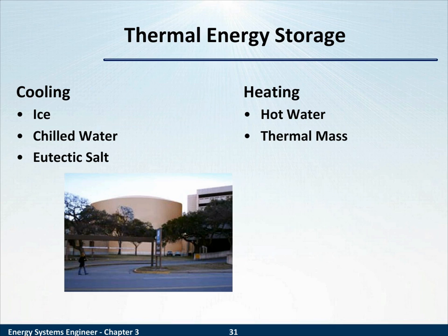We have now a couple slides on thermal energy storage. Something to consider right off the bat is why thermal energy storage. Thermal energy storage does not save in energy consumption. If you were to create cold water, store it in this big brown tank in the picture, and then use it later, it did not save in energy consumption. What it did save, or what it is likely to have saved, is in demand charges.